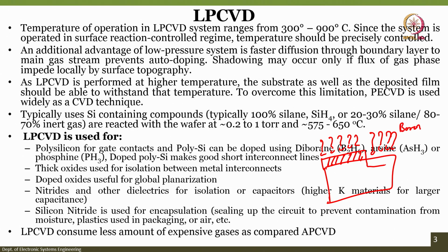Then boron will penetrate into silicon here, causing P plus, assuming that there is an N type substrate, but boron would not be able to penetrate in this region because silicon dioxide is present. This silicon dioxide can work as a masking oxide. So, that is the second thing that we need to understand.